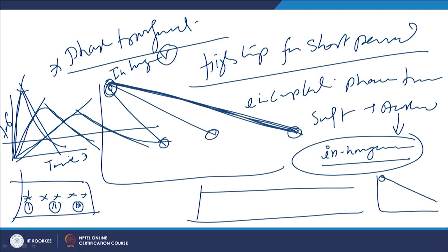One which is being cooled very slowly will lead to the formation of coarse pearlite. One which is cooled at a higher rate will lead to fine pearlite. A further higher cooling rate may lead to fine pearlite and martensite. Further higher cooling rate may lead to the formation of complete martensite.